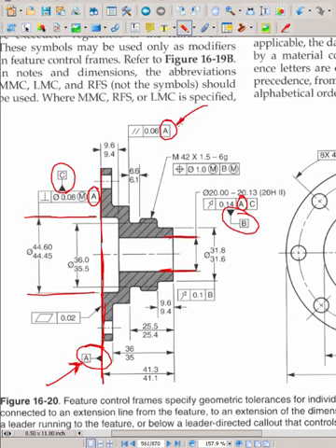Okay? First of all, we look at the symbol and we look back in our text and we find that that is an orientation tolerance for parallelism. Here's the value of the tolerance. This is the reference of the datum.